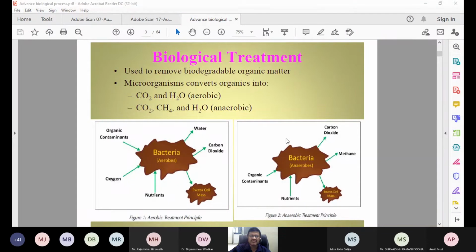So fine. So what is BOD indirectly giving? It is giving you the organic matter present in the wastewater. And how are we doing this test? We are utilizing the bacteria in the bottle to find out the organic matter. COD is the same, but we are not utilizing bacteria; we utilize a chemical like potassium dichromate, K2Cr2O7, which is a very strong oxidizing agent.